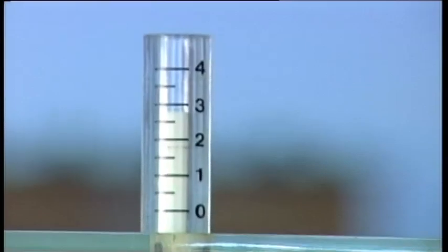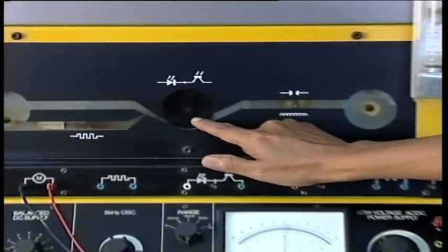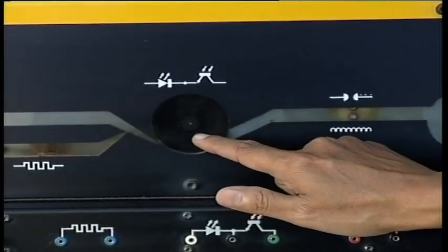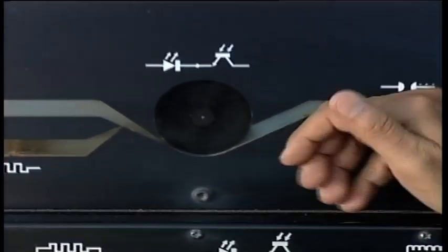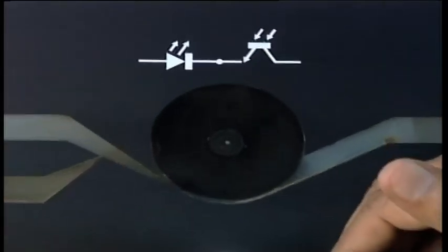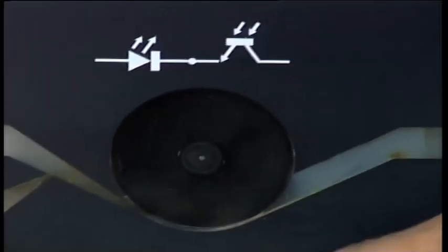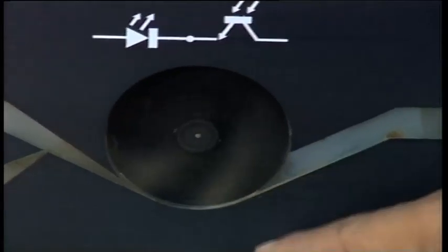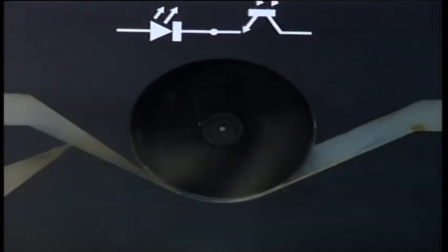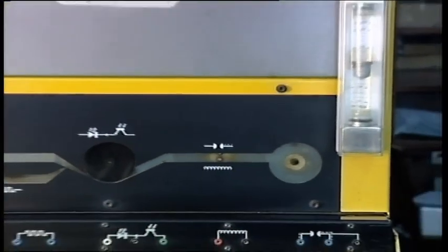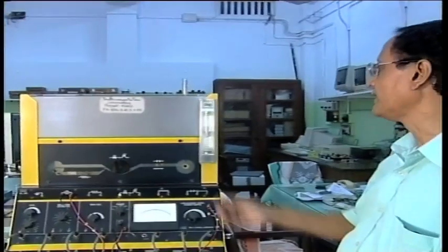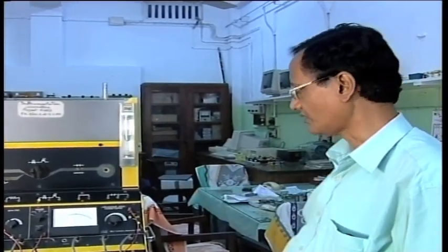And you can see here, interestingly, this is one electro-optic flow meter. If I go to the back side, you can see that there are 4 spots and there are lights falling on the flow meter, and for each complete rotation I am getting 4 pulses. So suppose I have 10 rotations, accordingly I can calculate how much the flow is moving. So it has a direct electrical output. Otherwise, you can see here this flow meter has no electrical output.